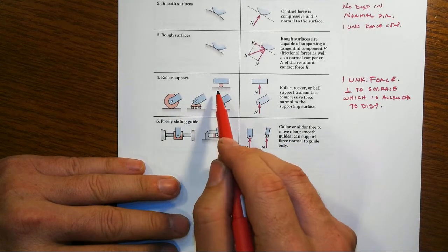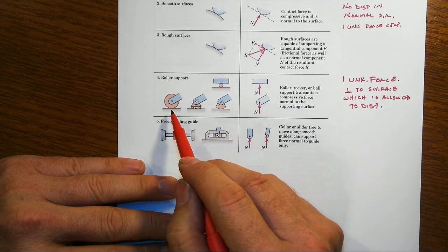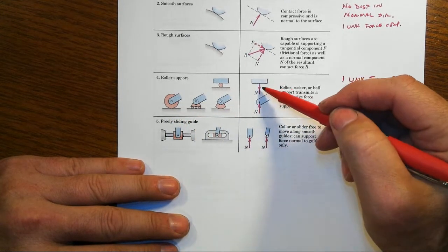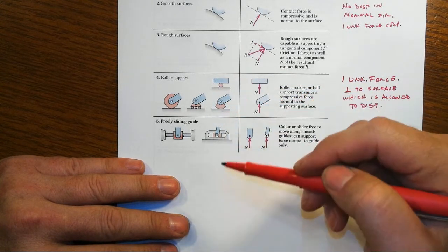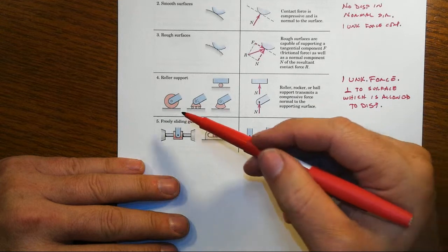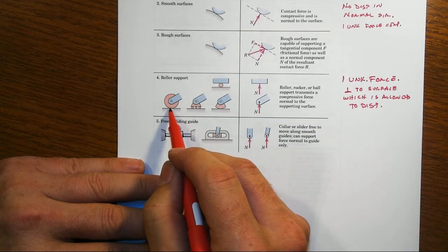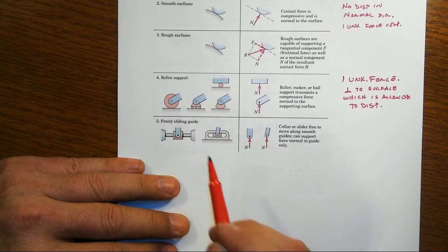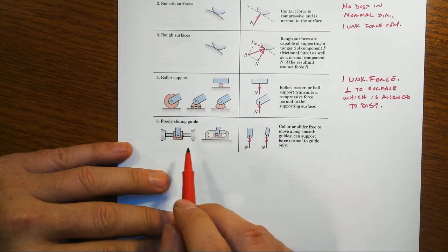Now, sometimes people get confused. They take these little diagrams a little bit too literally. In each and every case, depending on the author, but in most authors' textbooks, they are indicating here just a simple symbolic representation. There is no displacement up or down on this thing. So if this thing tries to lift off, there's a hold down force as well, even though you might not initially think about it because you think you see a wheel and gee, I can lift the wheel off of that like a shopping cart. And if you literally do mean that, well, then it does mean you only have a compressive force between those two parts. But generally speaking, we don't mean that. We mean that there's a hold down potential as well. Might depend just a little bit on the problem statement and that particular author and the graphic artist.